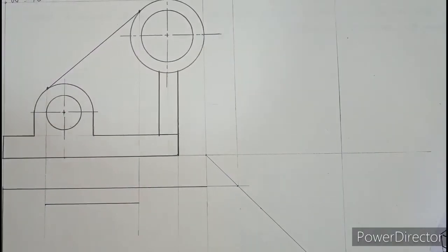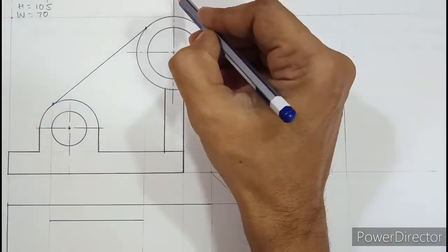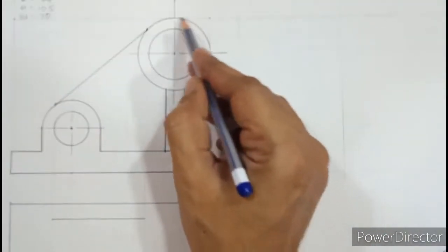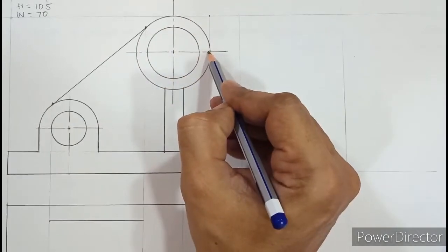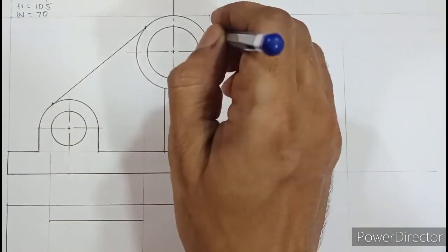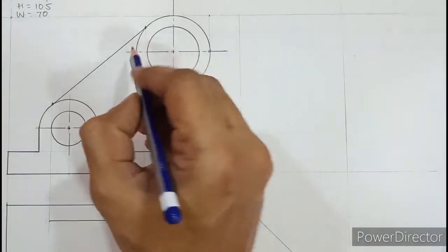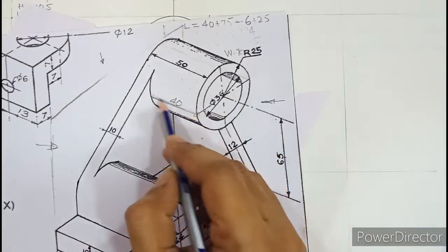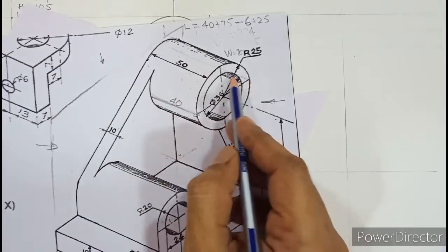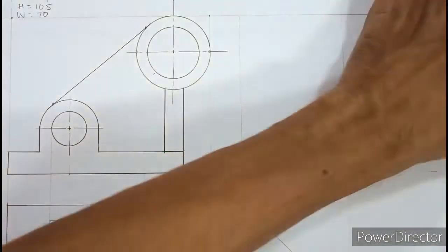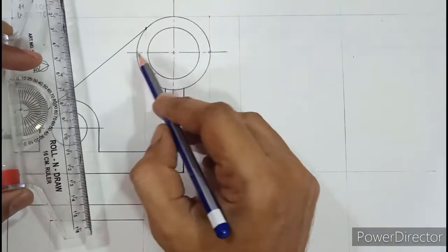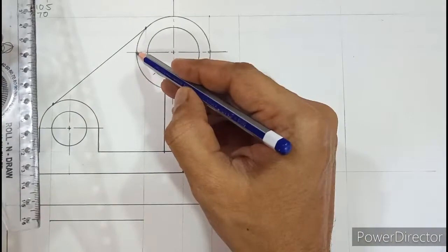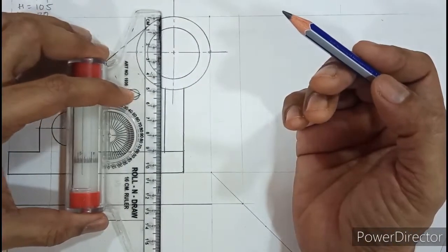So now moving further, in the top view when you observe, you can see this circular surface. So the right side point is 50 millimeter deep, whereas the left one is only 40 mm deep. How did I come to know? From the question, that this is 40 millimeter deep and the opposite one is 50 millimeter deep. So let us project this to the diameter of the circle. So the right side is already projected. The left side boundary needs to be projected. So from here I will align the scale.